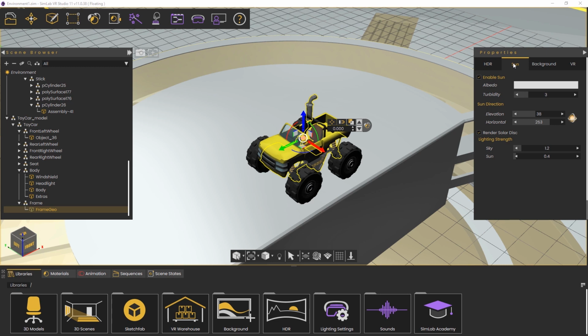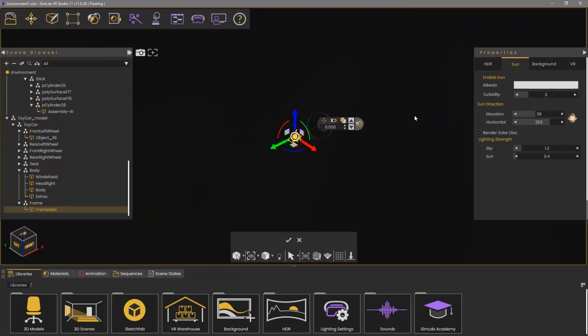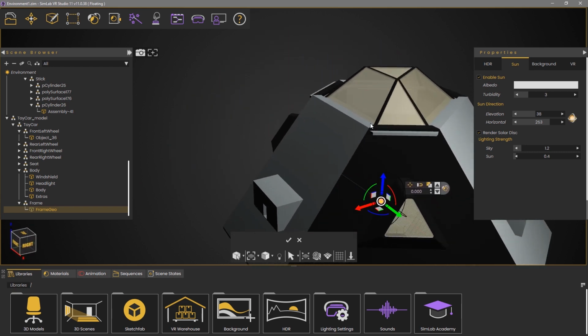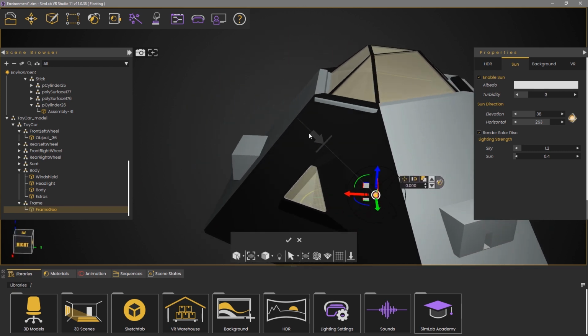You can change the elevation and horizontal value of the sun to change its location in the sky, which directly affects the angle at which the sun rays enter the scene. You can also click the icon next to the slider to display the interactive sun transformation tool. From the Transformation tool, rotate the white arrow in the direction you want the sun rays to travel along, then click the check mark to confirm the direction.